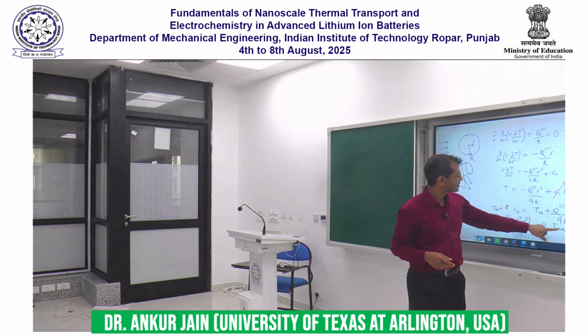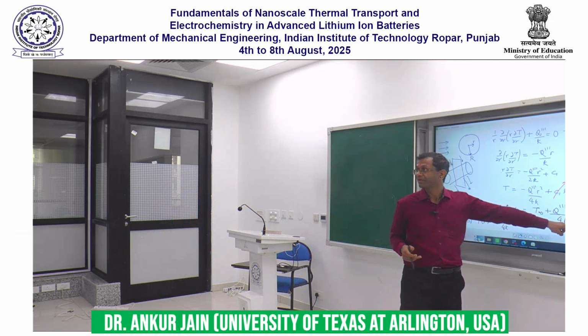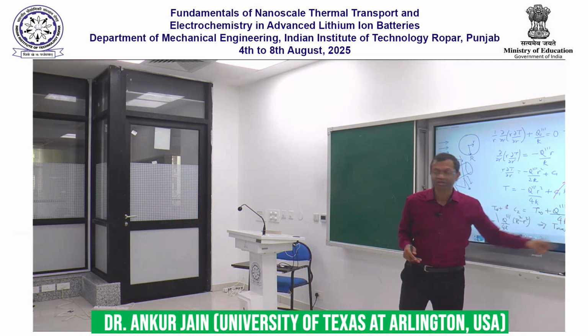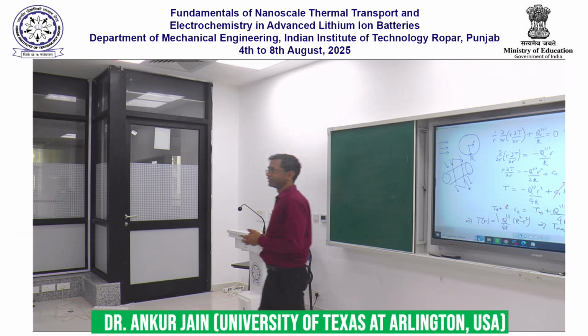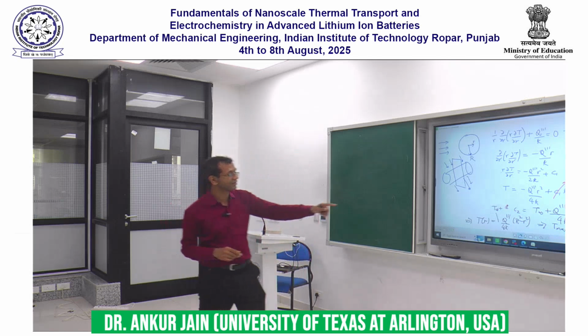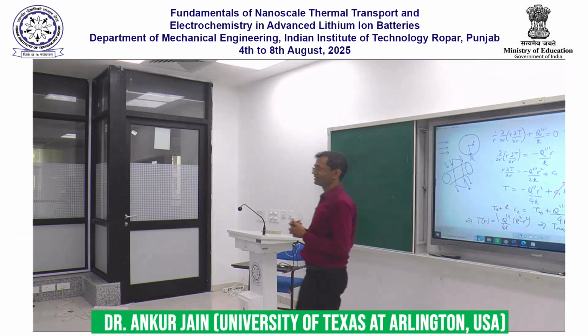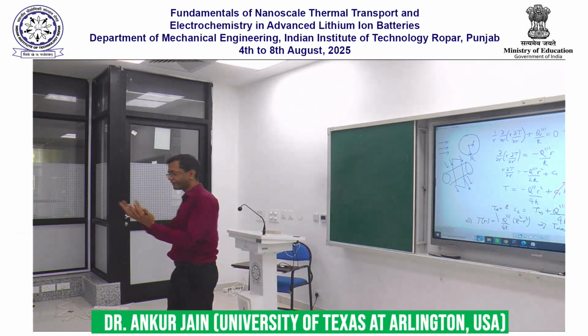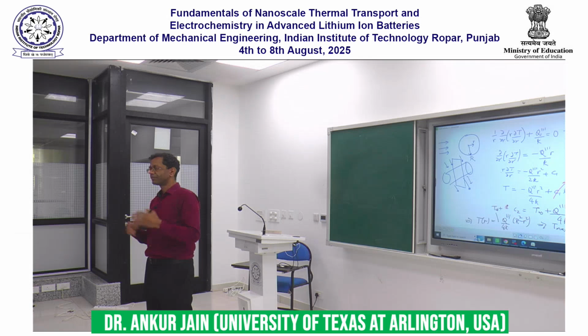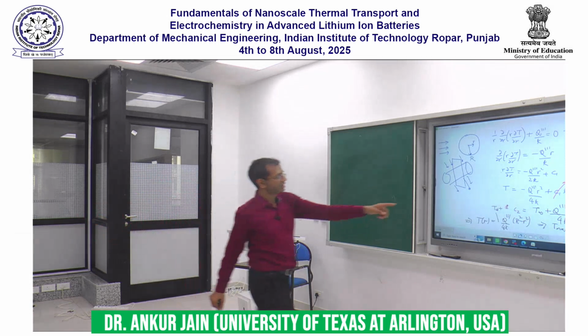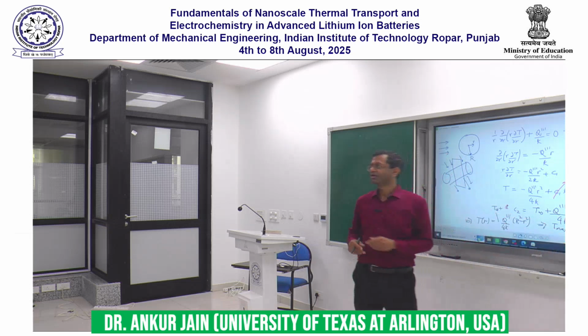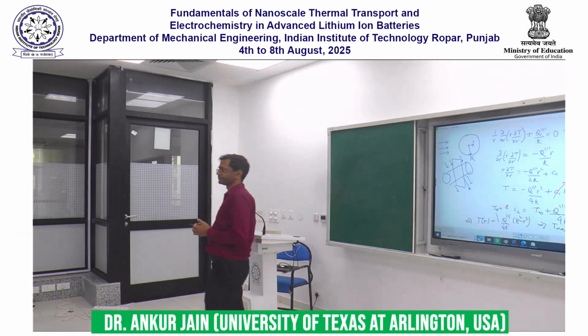And the temperature rise also depends on Q triple prime, the radius of the cell, and the thermal conductivity of the cell. This tells me that the higher the thermal conductivity, the lower will be the temperature of the cell. So if I have two candidate cells from two different companies whose thermal conductivities I have measured to be two different values, I really would like to go with the one that has the higher thermal conductivity.